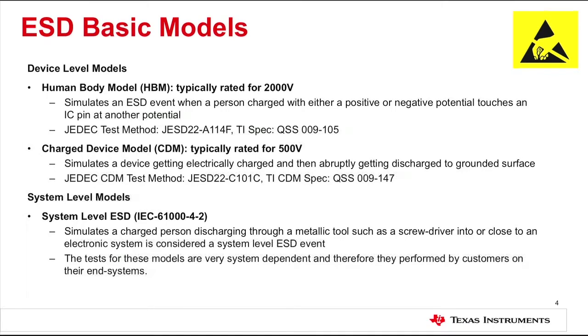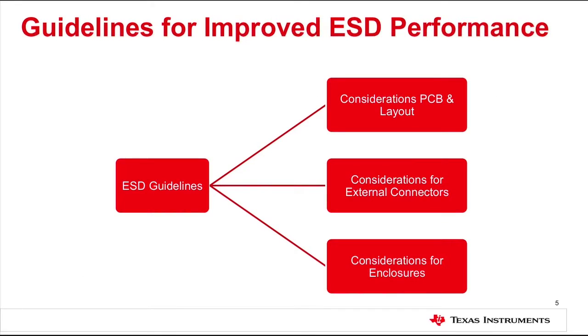Speaking about IEC 61000-4-2 specifically, it simulates a charged person discharging through a metallic tool such as a screwdriver into or close to an electronic system. The IEC ESD testing is very system dependent and therefore it is usually performed by customers on their own end systems. Next, I'd like to share some system design guidelines with you for improved ESD performance.